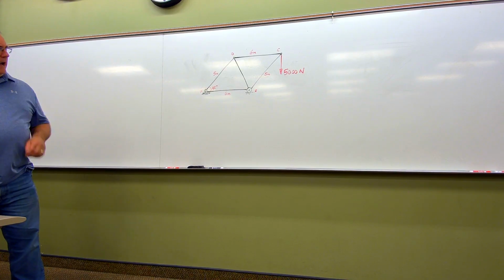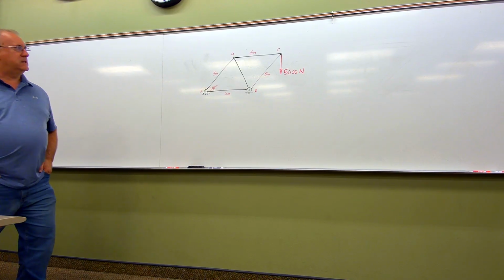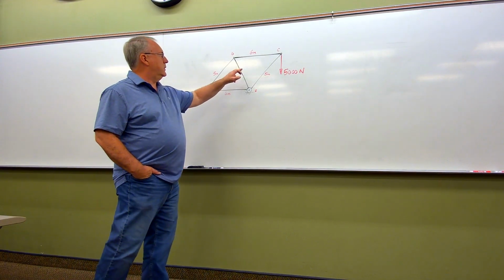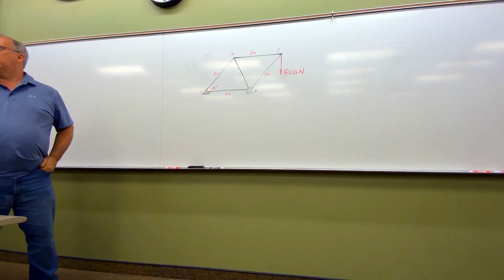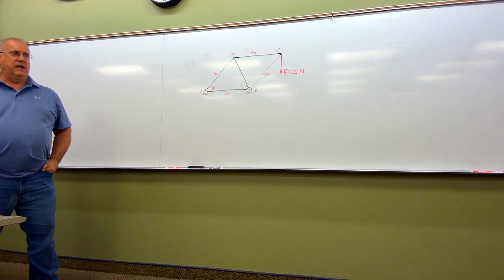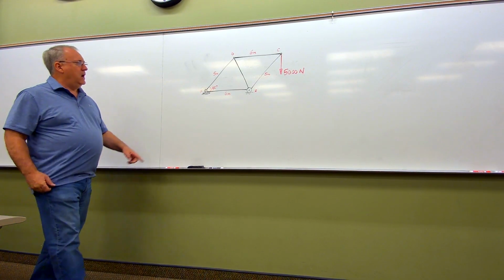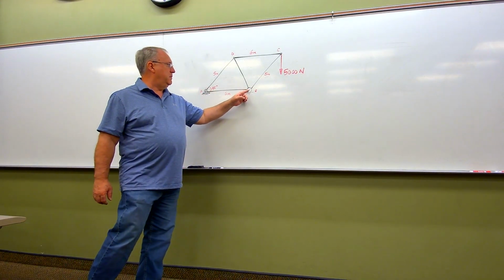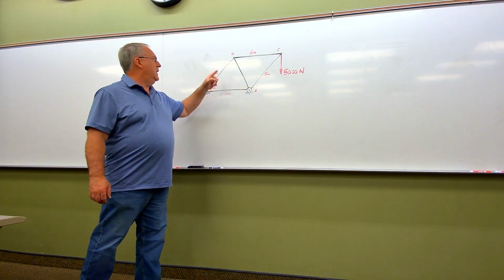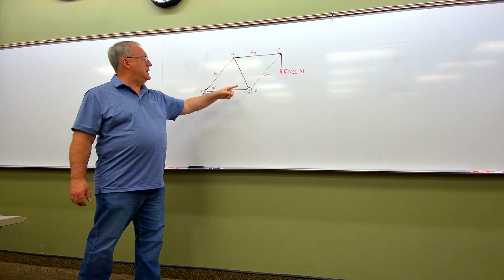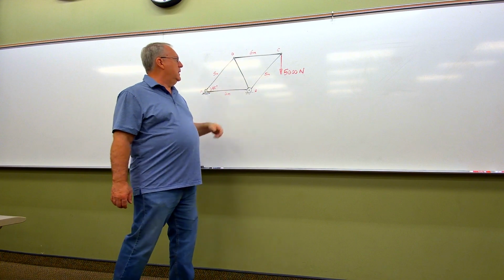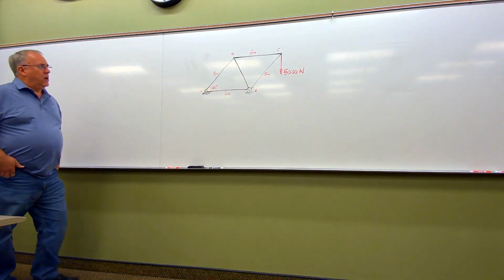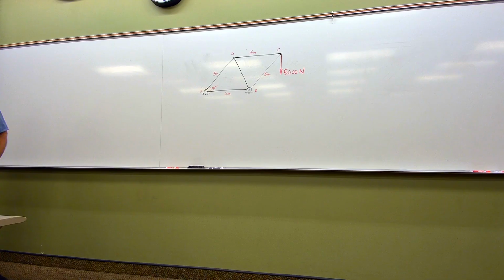So there's that. This truss here can be defined by a grand total of 1, 2, 3, 4, 5 members, and we usually name the members in accordance with the pins. So for example, if this is pin A and that's pin B right there, then that's member AB. If this is pin D, then there's member AD. Here's DB or BD, whichever way you want to go. DC, CD, same thing. BC, like so. So, 5 interconnected, 2 force members.